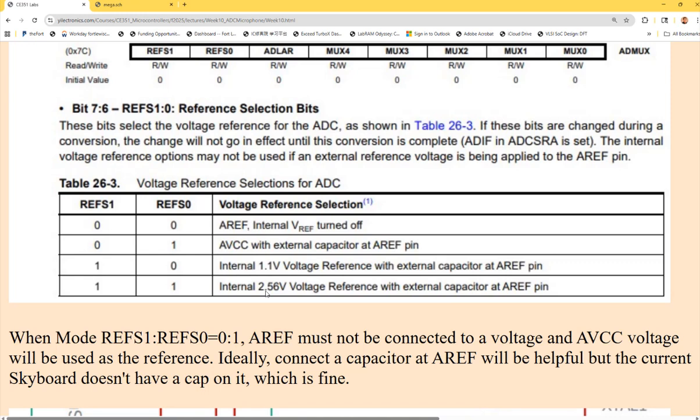No, right? If you want to decrease the smallest voltage to be detected, what can you do? You can reduce the reference voltage to 1 volt. It's going to be 1 volt divided by 2 to the 10th, which will give you about 1 millivolt as the smallest voltage to be detected, depending on your application.